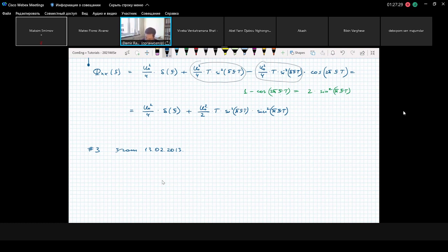And then we have an expression for the antipodal signal S1 of t, given as basis function psi1 times square root of E_b times the summation, from minus infinity to infinity, of z of n times delta t minus n capital T_b, and we have this sequence of